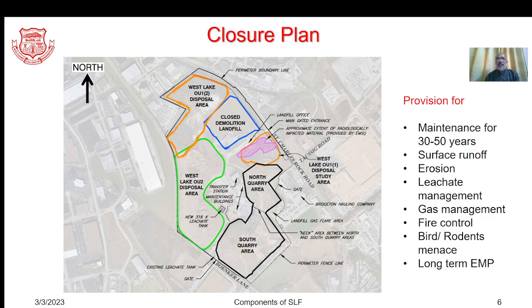Through the phases of these landfills, it is quite probable that it would start emitting methane, and if it is not properly controlled and it is leaking through the surfaces, as it comes in contact with the atmosphere, due to the heat and the temperature, it may catch fire.